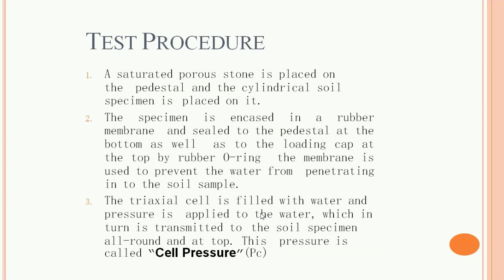So the objective of the triaxial compression test is to determine the shear strength of the soil under lateral confinement. An attempt is made to simulate the confining pressure observed in a loaded soil mass. In the test setup, it is possible to provide uniform fluid confining pressure only.